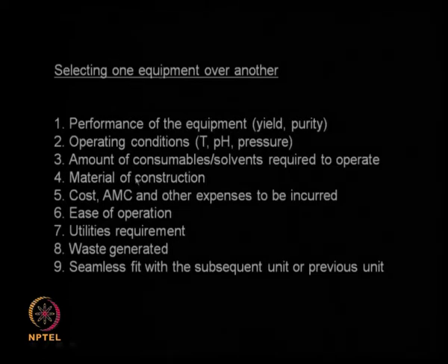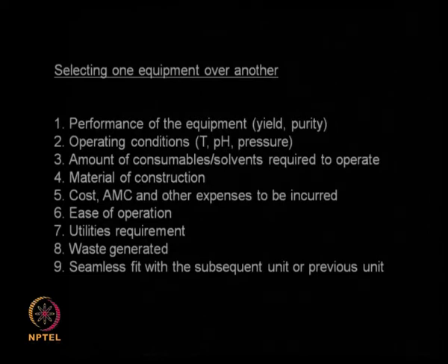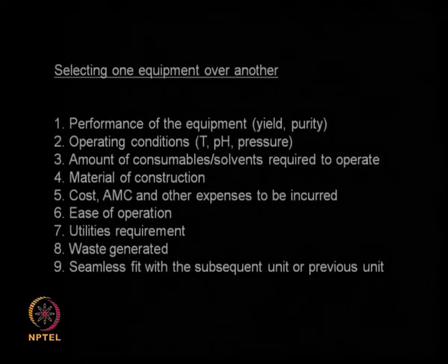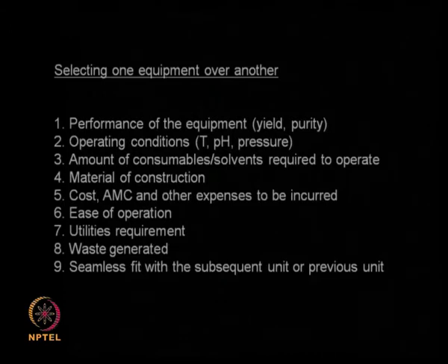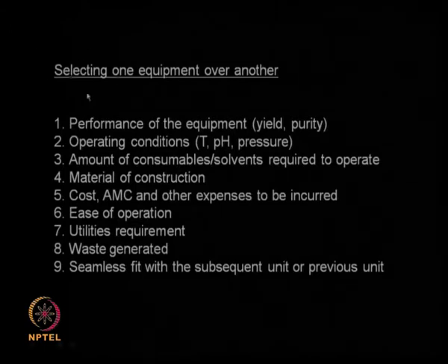Material of construction, can I operate with a mild steel, do I require stainless steel, do I require glass lined steel, do I require titanium. So each of these materials of construction leads to different total cost of the equipment. The cost of the equipment will depend upon the type of material I select. So what material of construction am I going to use, that is one of the important parameters when I am